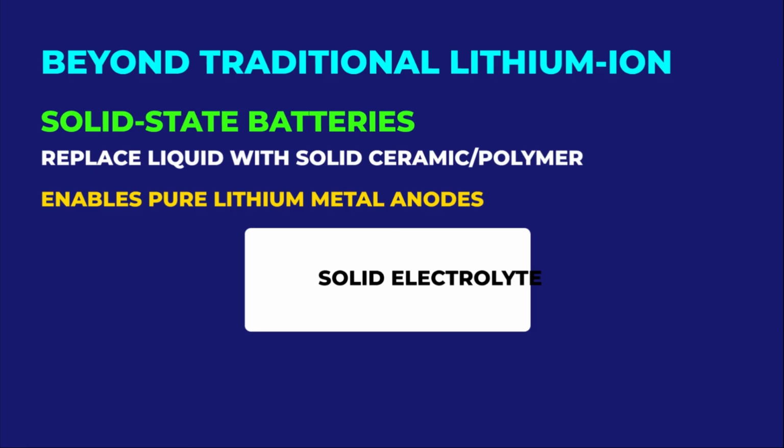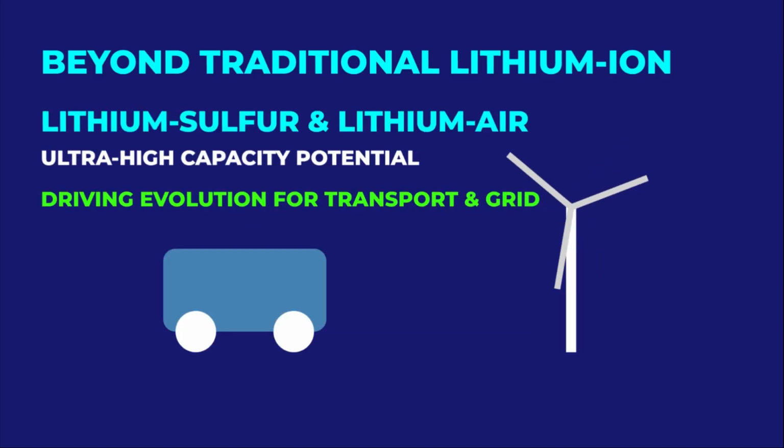Another major shift is the development of solid-state batteries, which replace the liquid electrolyte with a solid ceramic or polymer conductor. This change eliminates flammability and potentially allows for the use of pure lithium metal anodes, which would drastically increase energy density. Lithium-sulfur and lithium-air chemistries are also under investigation for their even higher theoretical capacities, though they face challenges with conductivity and chemical stability. These advancements in intercalation and conversion chemistry continue to drive the evolution of energy storage for transportation and the electric grid.